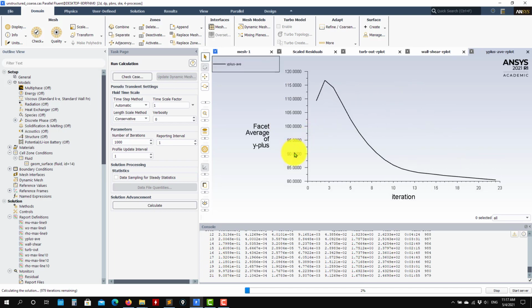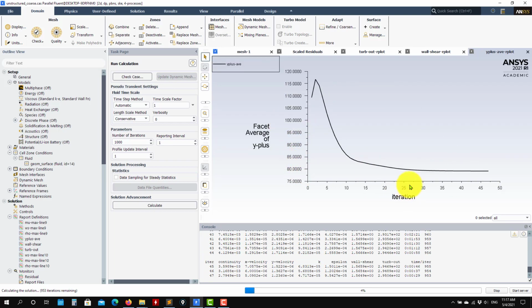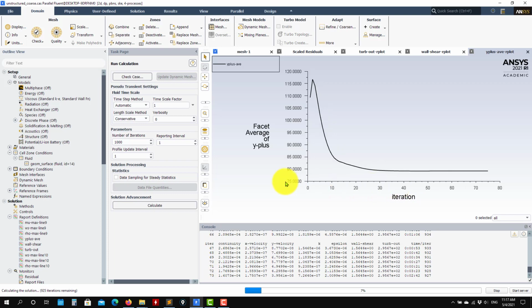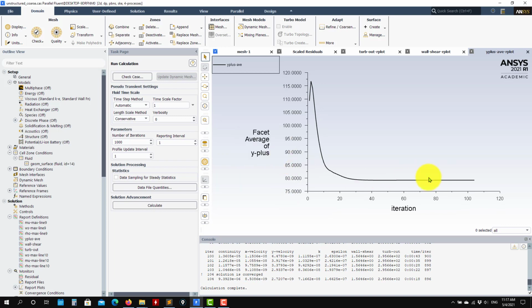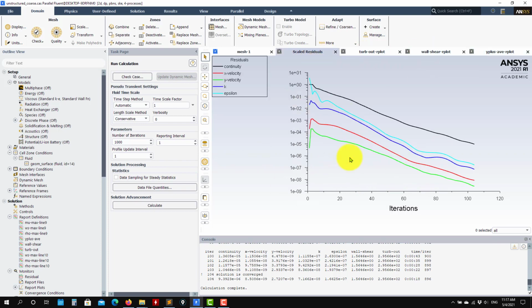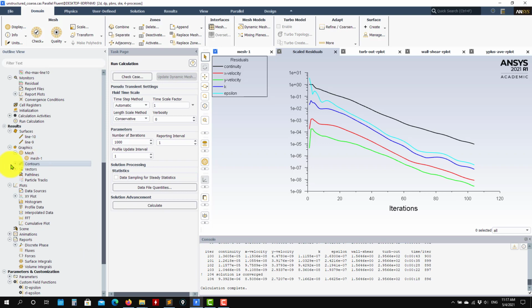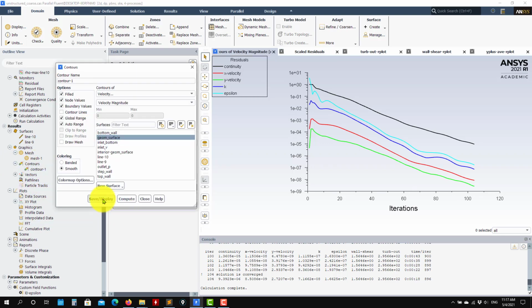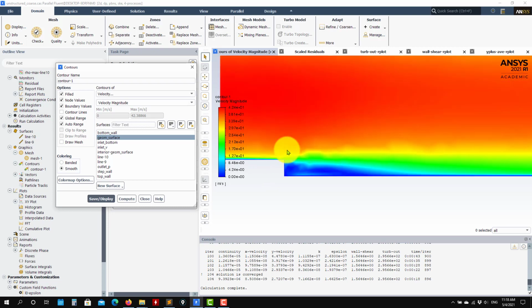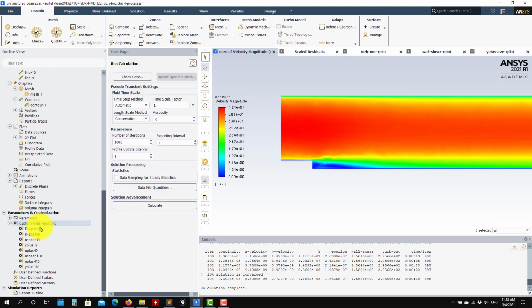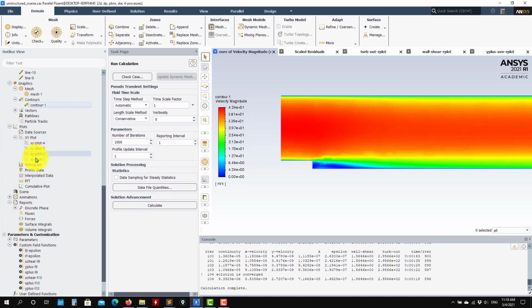See that our y plus is about 80. Usually if you want to use y plus wall functions, you should aim for values between 60 and 100. That will be the ideal one, but the upper limit depends on your global Reynolds number. So now we have a solution, everything fine. Let's see some colors. See that immediately you see the influence of the cell type in your solution, but we want to look at the solution in here.